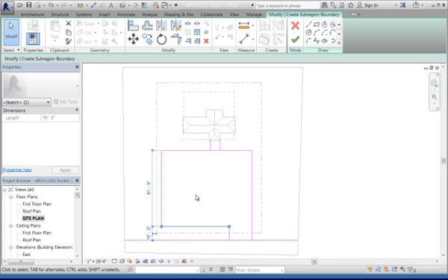Turn-in radius is 15 feet. That's talking about from the street. Median and curb radius is 2 feet. Parking spaces are 9 by 18 and must contain wheel stops. So turn-in radius is going to be out here.